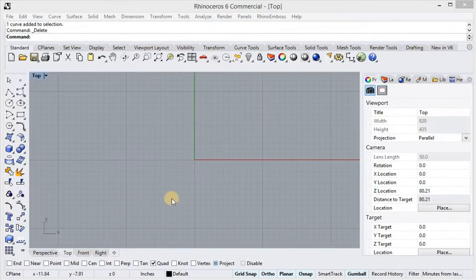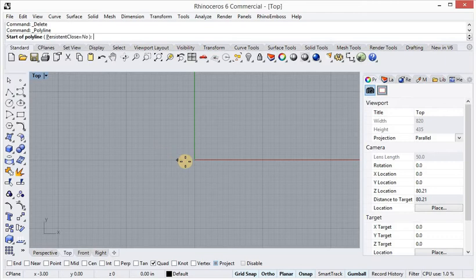In this lesson, I will teach you how we can convert or change these line shapes into 3D objects. Let's start with this Polyline tool. Click this tool and click in the viewport anywhere. I already told you it is just for practice, so you can start from anywhere. Make this line segment 10 inch. Press 10 on the keyboard. Now you can see it is stuck at 10 inch.